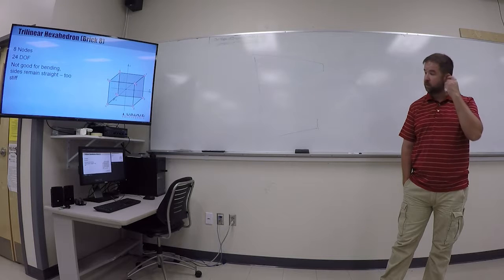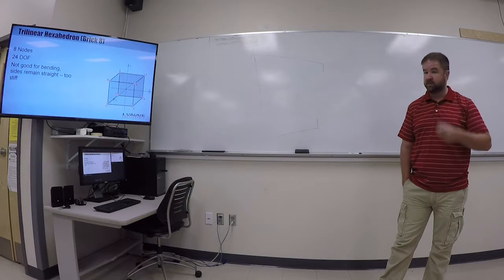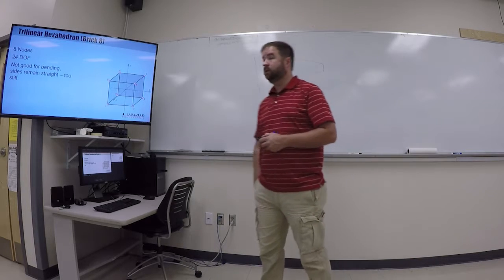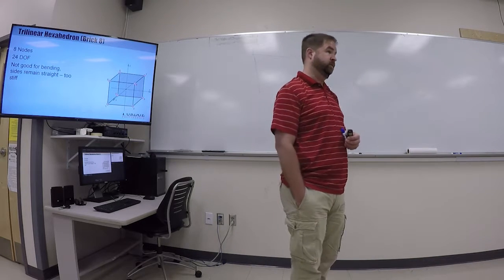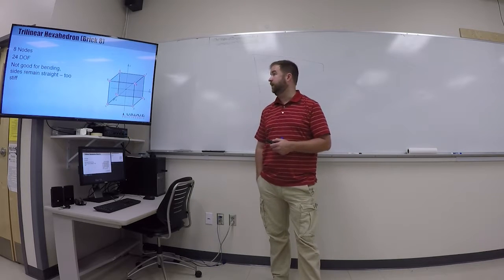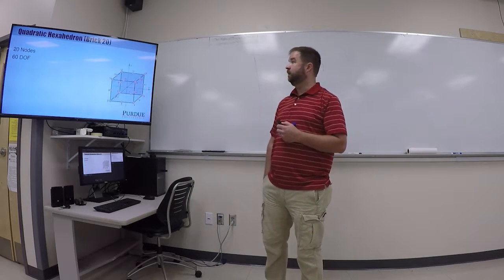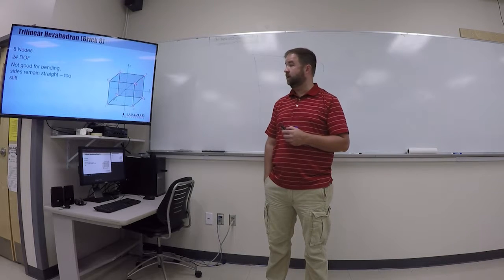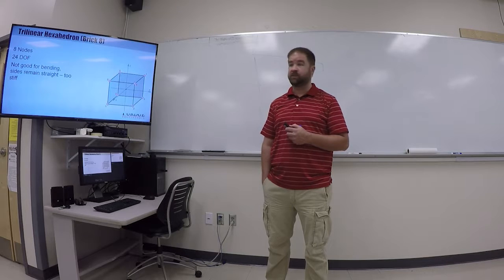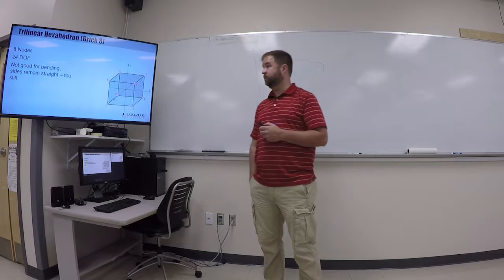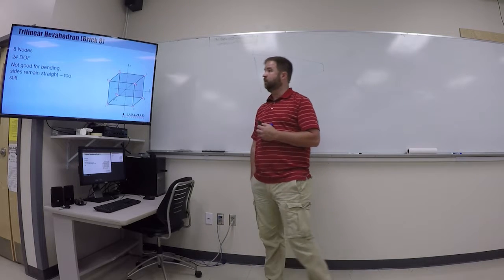We also have element shapes that are rectangular. SolidWorks does not have this, but if you use software like ANSYS, you can specify hexahedrons, which are brick shapes, often referred to as brick 8, and then brick 20. Okay, same concept, except we're using rectangular sides to our shapes. We end up with 8 nodes on the brick 8, and 8 times 3 is 24 degrees of freedom.